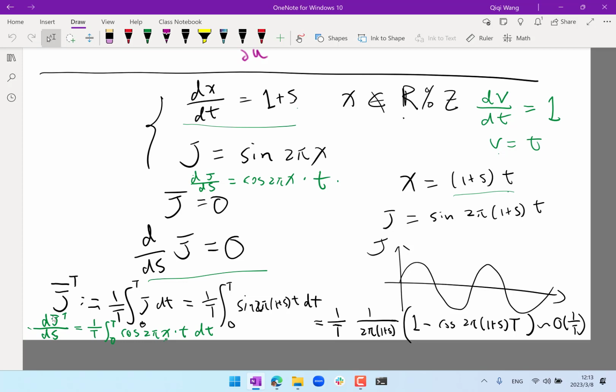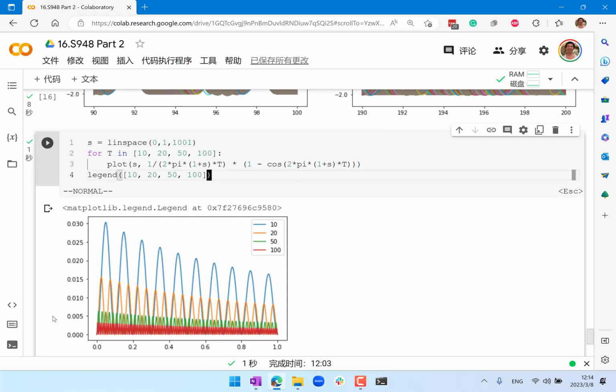If the frequency increases not as fast as the rate at which the magnitude decreases, then we have hope that the derivative is actually going to converge, right? That is basically what this plot shows. If instead of the magnitude going down linearly, it goes down, for example, quadratically, then not only would the magnitude go to 0, but the derivative would also go to 0. That is the goal of the windowing method.